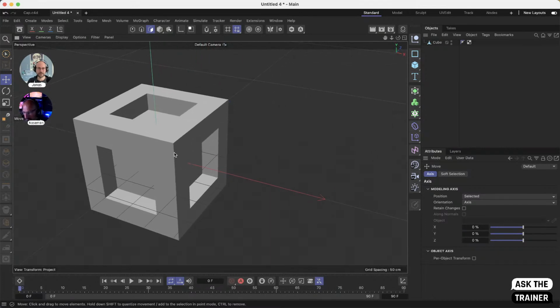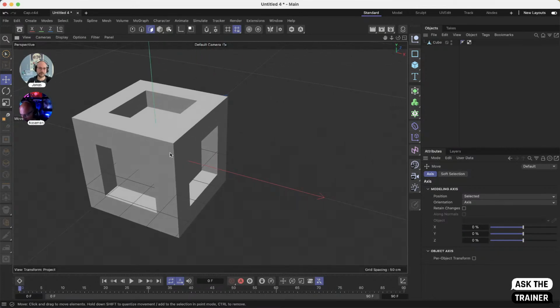First is, when I'm modeling, I always like to have screen space ambient occlusion activated. And the reason for that is, here you cannot really see where this one face or polygon is ending and where the others here are starting, because they are both planar and both pointing in the same direction. You don't see any difference here. You can assume it from this line here, but you don't see it.